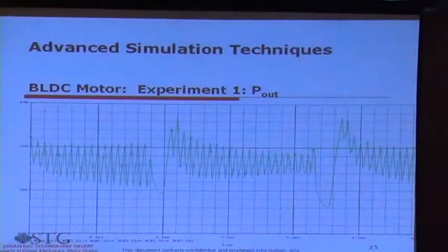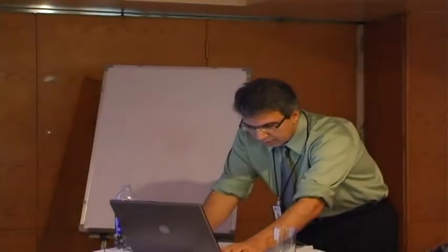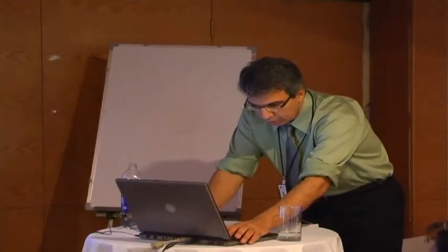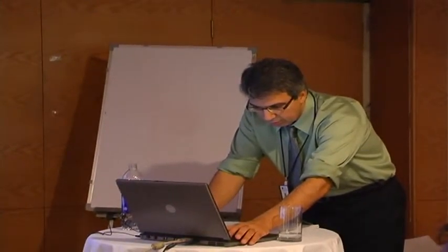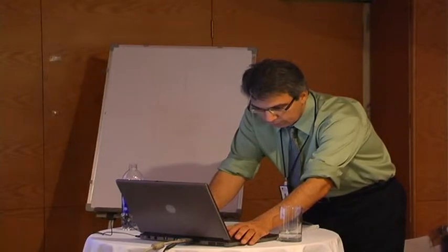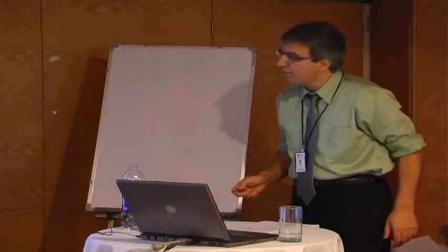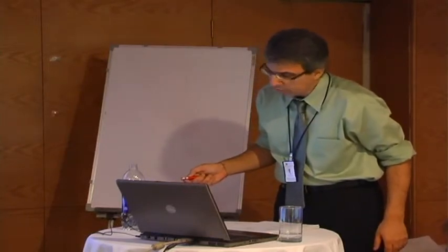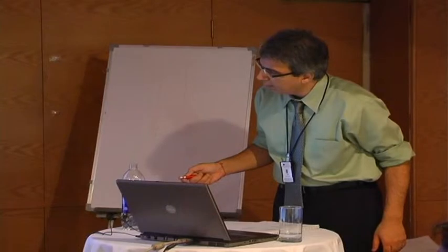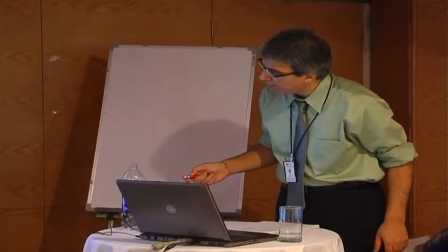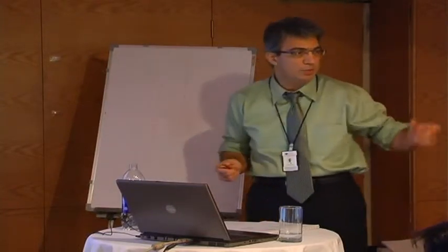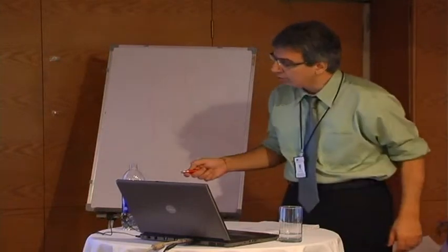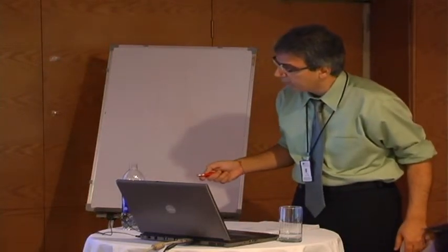And the way we have calculated this power, there is a power function in PSpice, and it's called W. So I'm going to just slide this up so you can see the power function. Here we calculate the power at a node, so it's W and 1, 2, 3, 4, 5, 6. So 6 sources which we talked about to build back EMF. So we compute the power from that point.